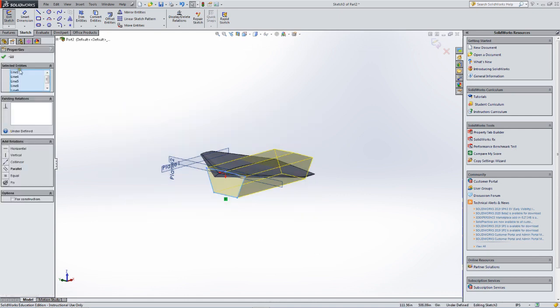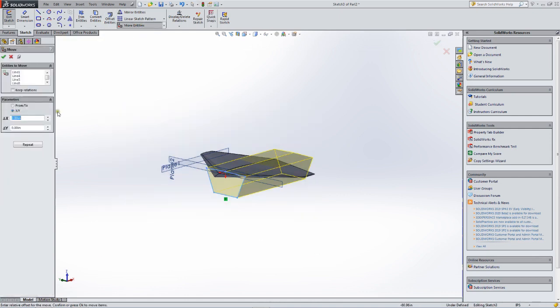We want to move it minus. Okay, so we're in a different plane. Y is, I think, positive or positive up. So I'm going to go -3 and see if that's right. Nope. So that's not right. When you start drawing in other planes, our nice X and Y axes don't work, and so sometimes there's a little trial and error. Let's try -3 this way. Yep. And then so it's +3. So it was what I said, positive, and you see these little axes here, positive down and positive right.